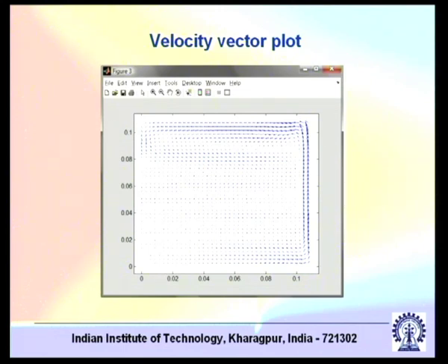you can use. So for example, this is a plot shown using MATLAB as a GUI interface. What you are doing here is using a MATLAB inbuilt function called quiver. If you have u and v as two velocity components, quiver(u, v) generates the velocity vector plots in MATLAB. This is just a generic example, but you can use different types of graphical user interface. For contour plots in MATLAB, you can use a similar function called contour.